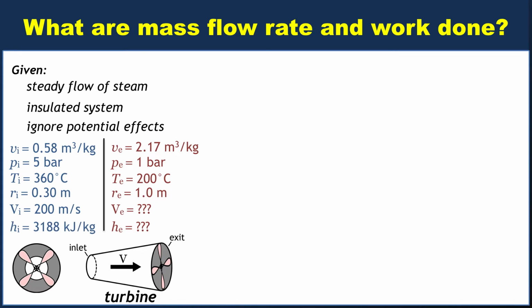The specific enthalpies are here. And note the units, I wrote them in. The specific enthalpy units are kilojoules per kilogram, so if we use these in a calculation, we'll have to worry about a factor of 1,000 creeping in.